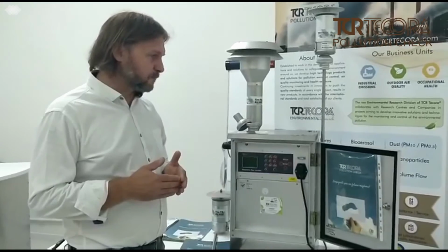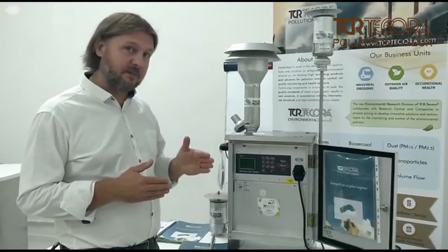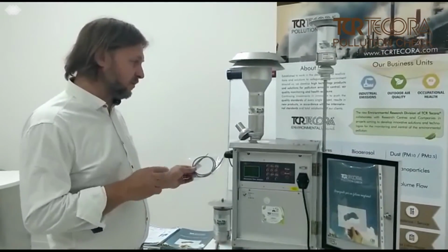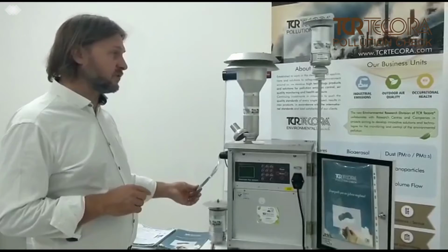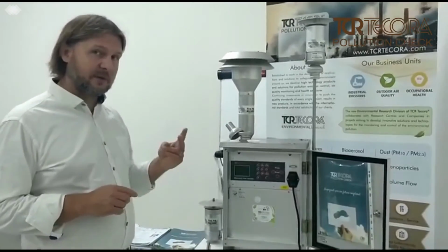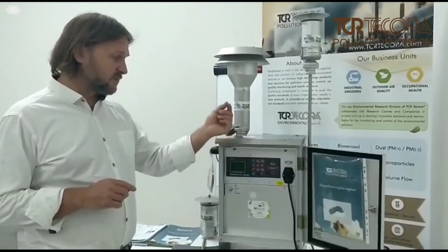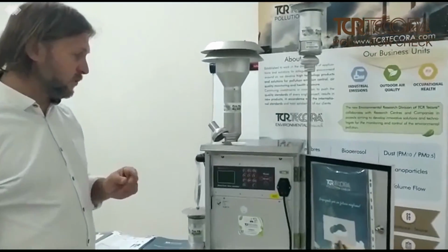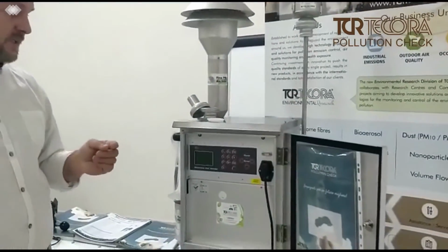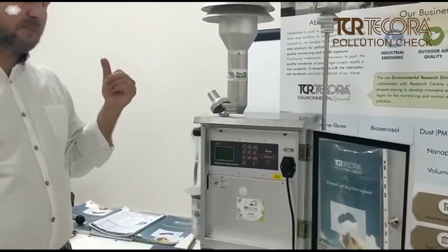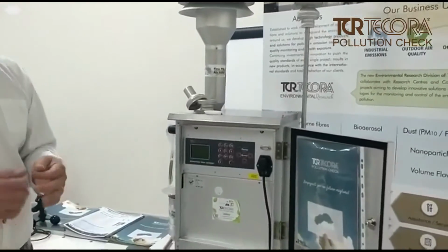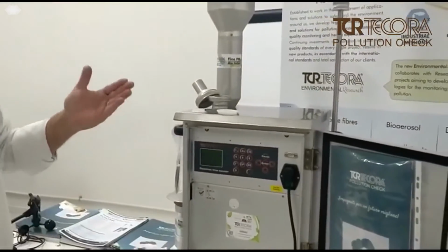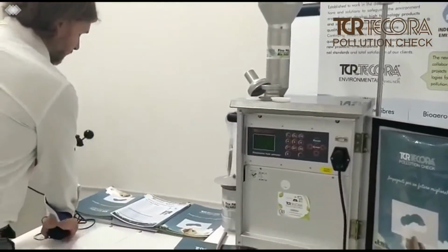And another important thing is the very stable calibration of the sensor. The system is equipped with 2 temperature sensors. One is the temperature sensor of the head condition, and the second temperature sensor is inside the machine that measures the air flow that is entering in the flow meter. And we have also 2 pressure sensors. One is dedicated to control the ambient pressure, and the second one is dedicated to control the pressure of the line. And more than this, the device can work also according to the weather condition.